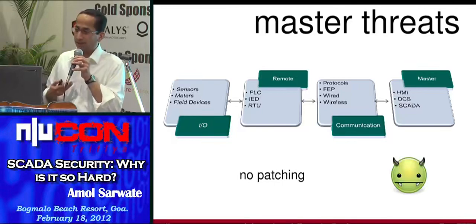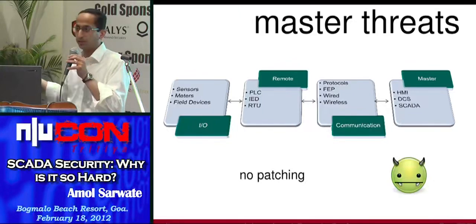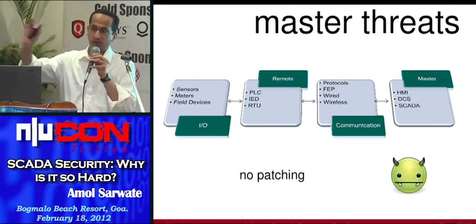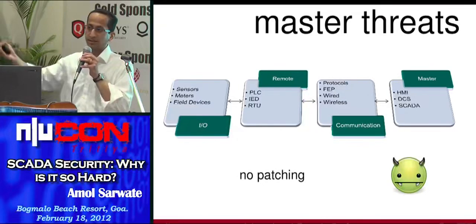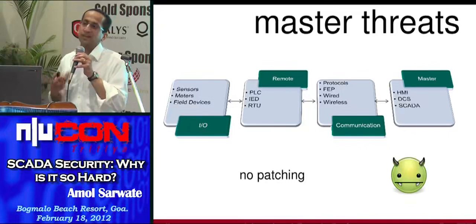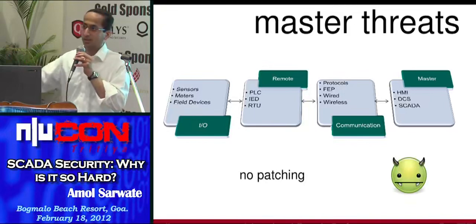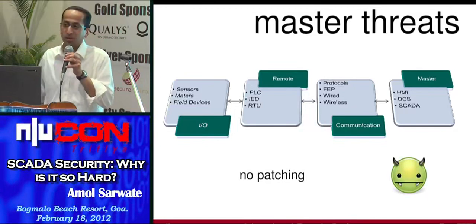So if I was a SCADA vendor, and a Microsoft patch comes in, I can easily patch it in my lab, see if my software works fine, and post it online on my website: it's okay, we have tested this patch, at least in this configuration, it is safe to apply. Then, as a SCADA owner, it will give me some confidence that I can apply this patch and the power will not go away or something drastic won't happen. But many vendors are not doing that, and therefore the SCADA owners have no choice but not to patch that system, because they don't want to take that risk.